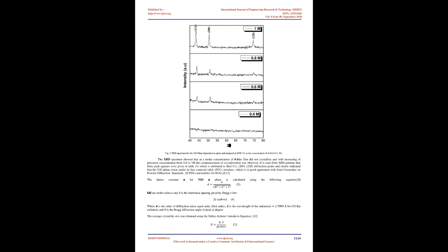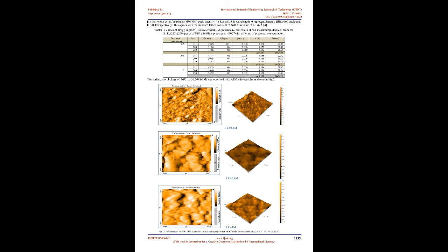Nickel oxide thin films are very important to be used in many scientific and technological applications. They have achieved great success when they were deposited on glass substrates in various physical and chemical ways. The most important ways are thermal spray, pulsed laser, chemical bath deposition. Nickel oxide films have some electrical and optical properties such as band gap in the range of 3.1 eV to 4 eV and electrical resistivity in the range of 10 to 10^6 Ω cm.